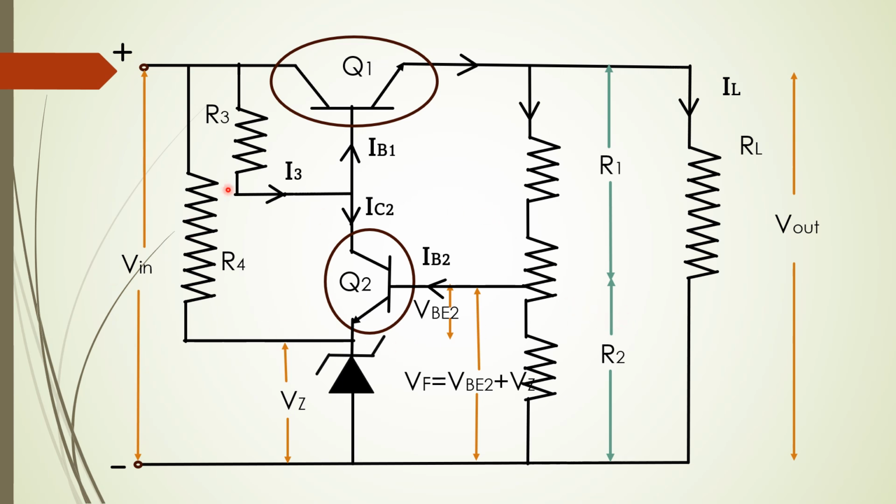To compensate and improve the circuit, feedback is included, which makes this a negative feedback regulator. In this entire circuit, we have one more transistor Q2 along with a variable resistance, a pot, and the resistances R3 and R4 that are now included in the circuit.